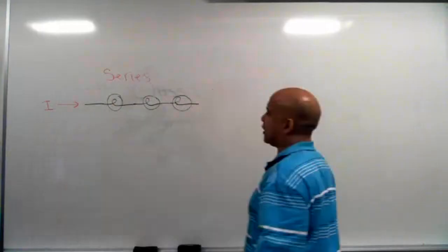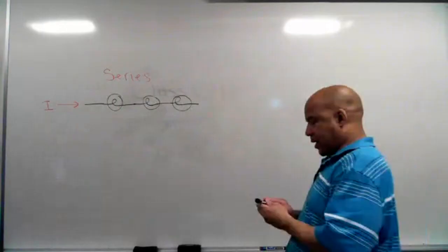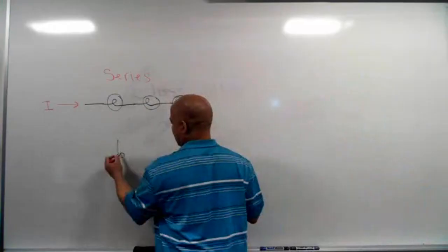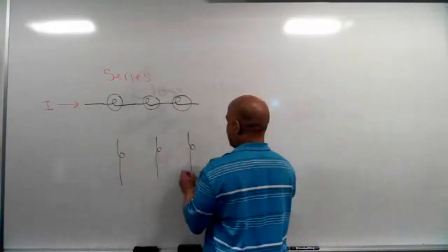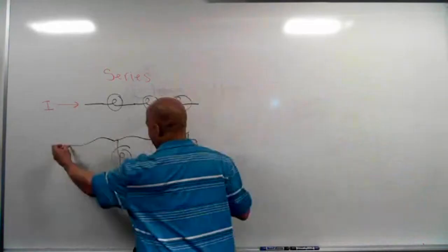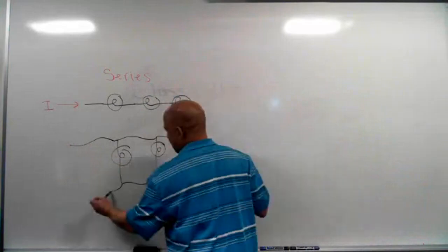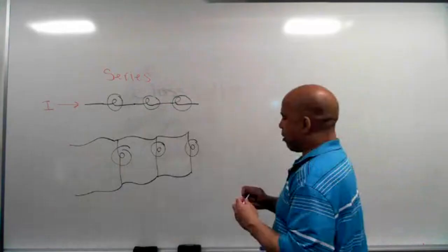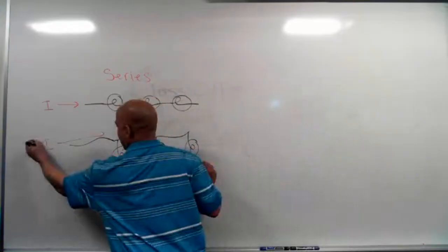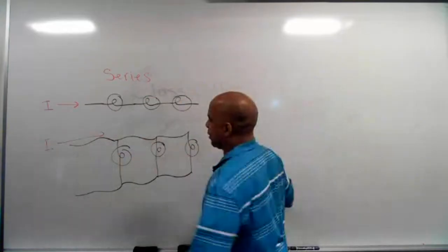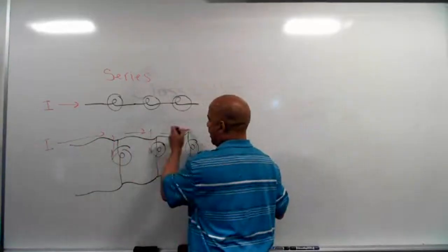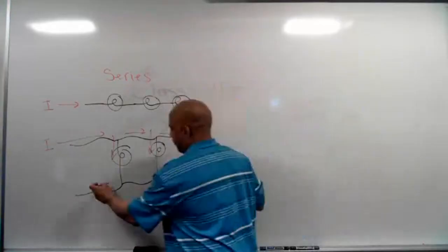So we'll look at series connections of devices. If I wanted to, though, I could take these 3 light bulbs and connect them like this. I can take a wire, connect the top of each bulb together. I can take a wire and connect the bottom of each bulb together. Now I can think about current flow into this circuit. Current can flow into this wire. Once it gets to that first light bulb, the current's going to start to split up. Some's going to go this way, some will go that way, it'll split again, and on the bottom it'll recombine and flow back out of the circuit.